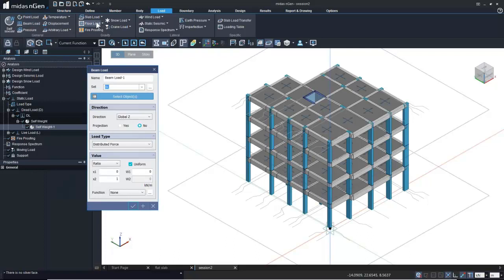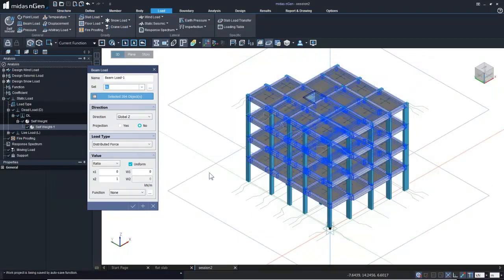So here we can see that the current function can have a selection of beams, columns, braces, subbeams, subcolumn members. If you do not want the columns to be selected, you can just check on the beams, click anywhere on the screen after checking on, and then select by making a box, and only the beam members will be selected, and you can provide over here the distributed force, say -1, and you can click on apply.